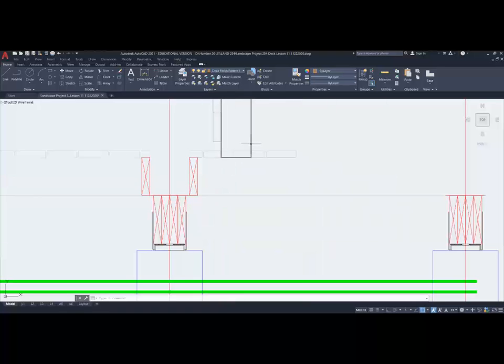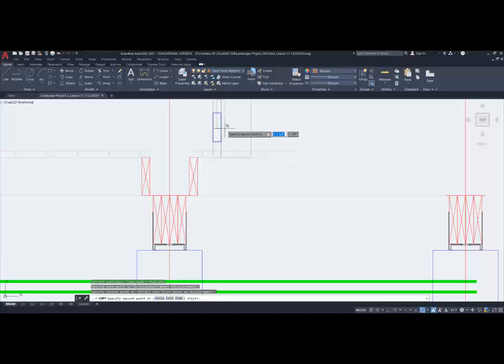This bottom piece here has to have a framing element at the bottom. Now I'm going to show this as a structural element so that it's easily seen. Let's copy this board here down in this corner, and then we'll rotate this from this corner. That's a minus 90-degree rotation. And that one will have an X drawn through it just to show that it's cut and it is framing.